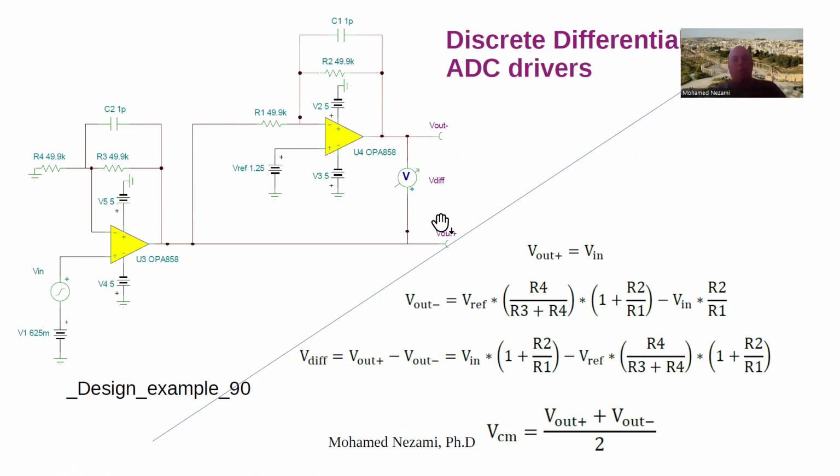Now, the Vout in this case is equal to the following. First of all, you have these two resistors, the ratio of those two resistors. This is an inverting amplifier, so that's these guys in here. That's this term, and this one is negative, of course. Now, as far as the reference voltage, which is in here, we have two things. This input, once it goes in here, has a gain of the ratio of these two resistors. I think these are reversed. So this one, the plus one, is really this ratio of these two resistors plus one. No, that's this case in here. I'm sorry, so this is correct.